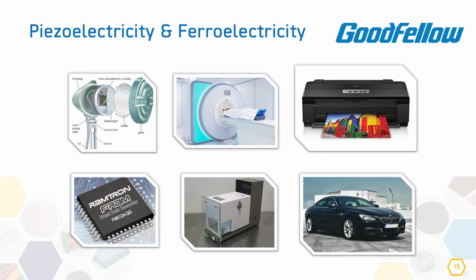So there are 5 applications for piezoelectric crystals, and one of a ferroelectric is ferroelectric rapid access memory. Now, as I said, a ferroelectric crystal can be polarized up or down. And for anyone who knows how data is recorded as 1, 0, 1, 0, it is up, down, up, down. So if we can set specific crystals to up or down, we can then read this afterwards as stored memory.